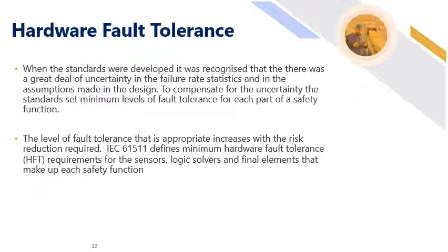Once we start needing a hardware fault tolerance of 1, that's when we need to start having redundancy in the architecture. So at least one more transmitter in the sensing element and at least one more final element, so an extra valve to do the shutoff.